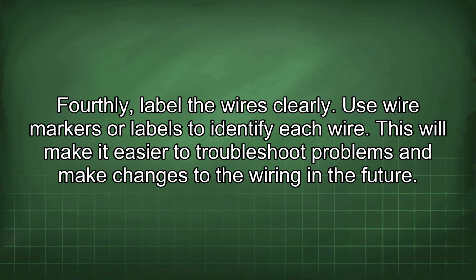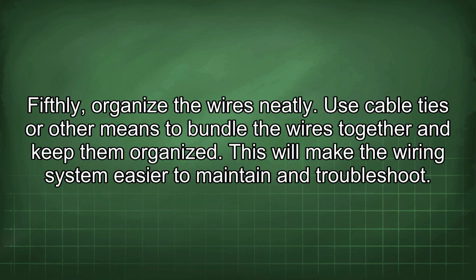This will make it easier to troubleshoot problems and make changes to the wiring in the future. Fifthly, organize the wires neatly. Use cable ties or other means to bundle the wires together and keep them organized. This will make the wiring system easier to maintain and troubleshoot.